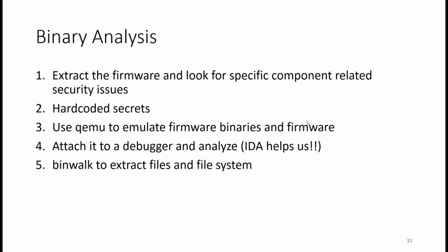So let's take an example where firmware is generating a runtime key which is used for communication. There you can emulate the firmware and find out in the functions how and where it is generating the key and at which place or offset of address it is storing it.